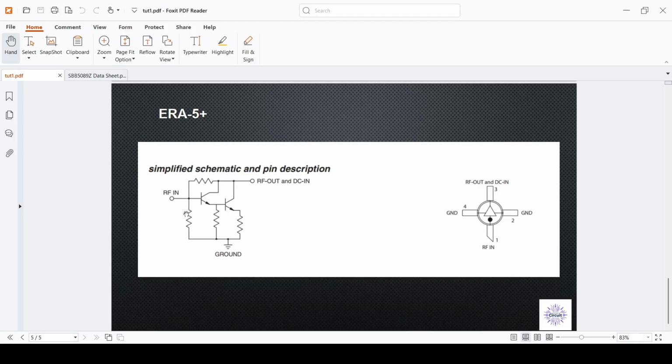One other thing is how we can generate the bias voltage for the base of this transistor. We can use a voltage divider through this resistor to generate the base voltage from the drain voltage. Sorry, I think this is a collector here in BJT, not drain. But anyway, it can be a MOSFET, and we call this drain. But one other interesting thing I want to discuss here is how we can generate a wideband matching, now that we have our biasing, we have our current gain.